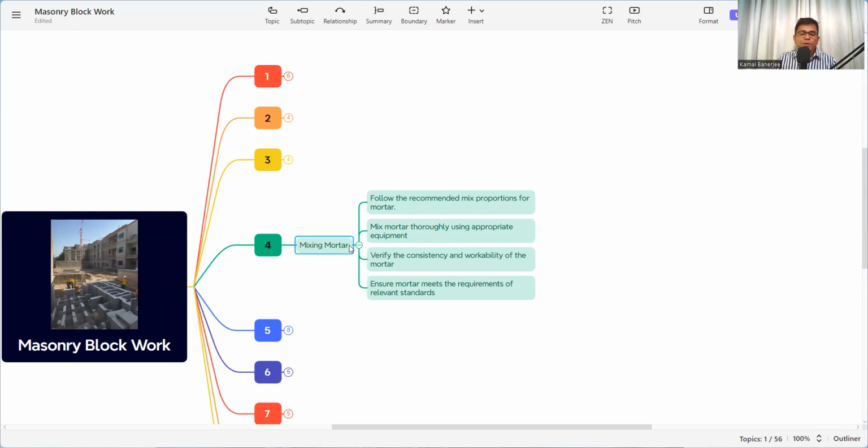Now there is another thing, we need to pour the water. Without the water the mix cannot be produced. And what is the proportion of the water? Whenever we are doing the blockwork, whenever we are preparing the mortar, we need to test the water required and the consistency of cement. That consistency we need to first finalize, and according to that we need to make a trial mix at the site, that for this 1:4 we need this much water. Accordingly, whenever we are doing the actual work, there will be a measuring cylinder, and according to the measuring cylinder we will pour the water into the mortar.